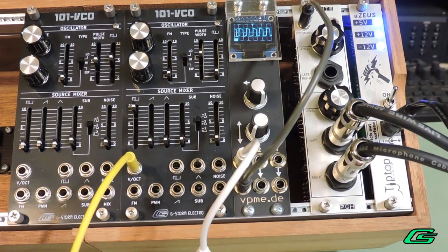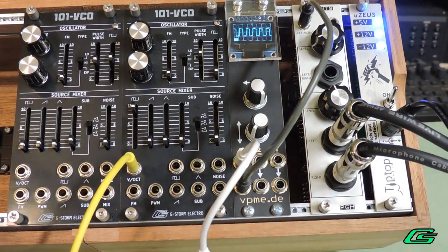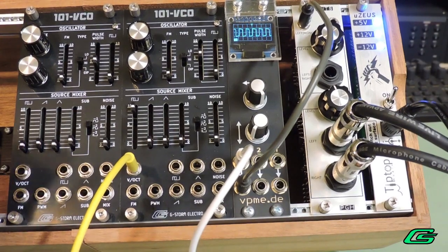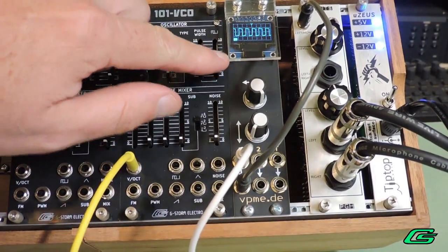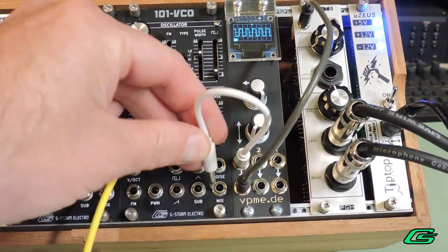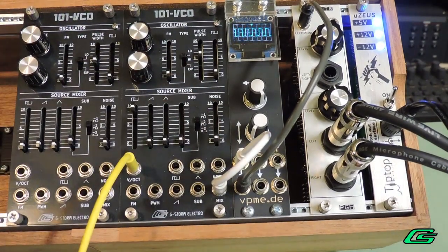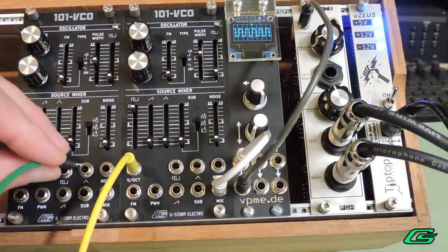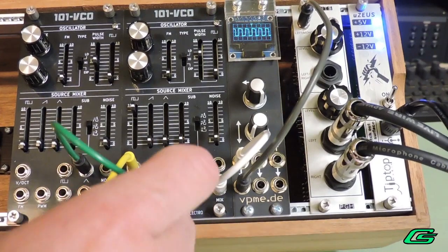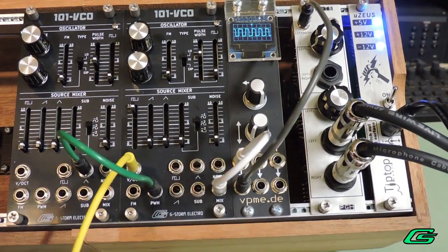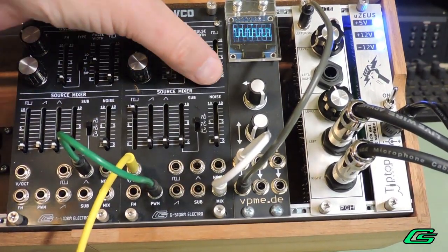Look here, another oscillator. I'm going to start out with a 50% duty cycle by setting the pulse width control in the middle. This other control is the pulse width modulation amount. Start with that set to 0. On my second oscillator, I'll turn the coarse frequency down low and plug its triangle output into the pulse width modulation input. Then turn up the PWM amount.